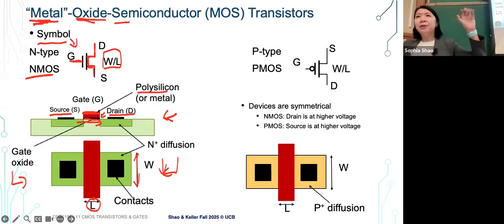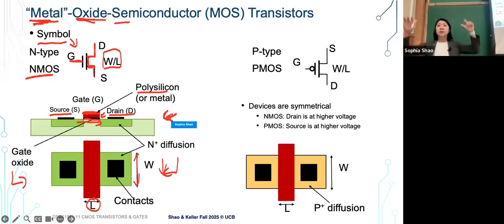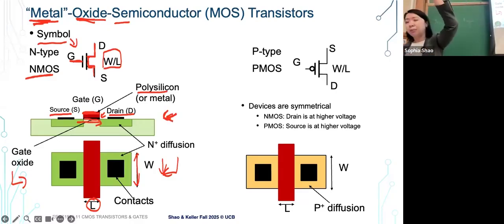This is at a very high level, like the three terminal devices and how they map into physical transistor behaviors. We'll talk about how we actually form those channels, but those are the three terminals. Again, the gate is the controlling part, applied to the metal layer or the poly layer, and then the other two terminals are forming a channel between source and drain. A little bit dry, but does it make sense at a very high level? We'll talk a little more about how we zoom into low level details later. Any questions, thoughts?